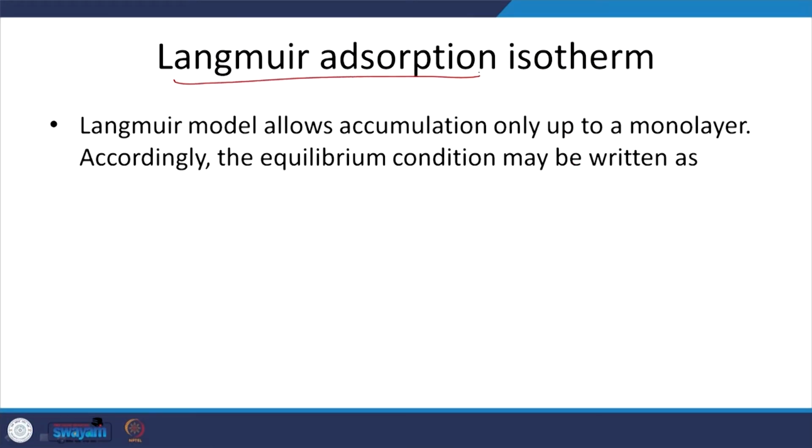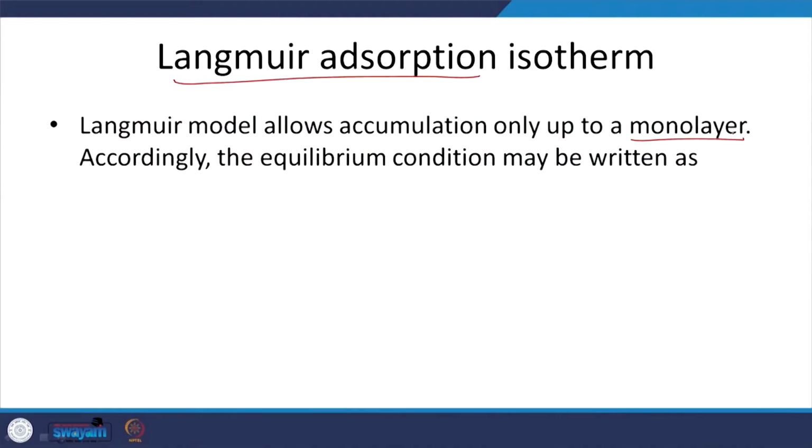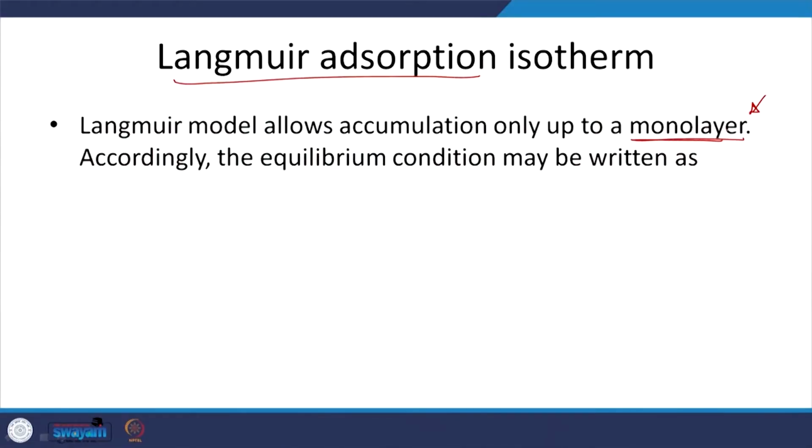So we are looking at this Langmuir adsorption, and one fundamental aspect is that we are assuming that we are only going to have one layer, or monolayer, of adsorption. So this is my site, and once all these sites have been taken up, that's it, you are not going to have other layers. As we discussed with respect to physical adsorption, where van der Waals forces of attraction are relevant, especially in the context of granular activated carbon, you can have different layers. It's not only going to be a monolayer, because it's relevant over larger or longer distances. So that's one aspect to keep in mind. We'll come back to that.